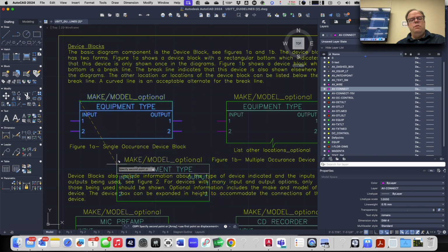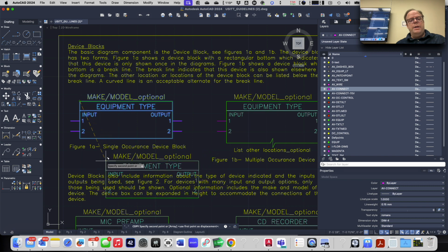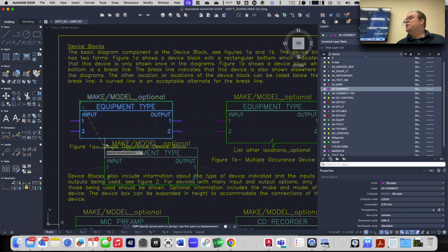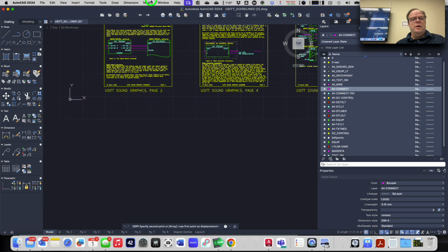Now look what happens. If I move my mouse, now I'm taking this thing with me. Okay? Now watch what happens. Now you're going to understand why I made you buy a mouse. Now scroll out and now click with the scroll wheel, pan the thing down, and look, it's still holding it. Okay? And with the object snap tracking, or the polar tracking, it's going to let me go straight down in a perfect vertical line. It'll tell me when I've snapped to vertical. Right? So I know I'm dropping it exactly down vertically.